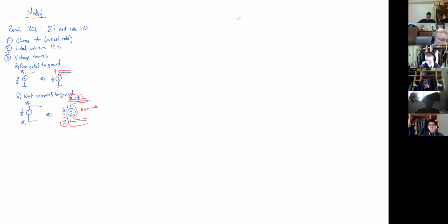All right, almost done. You'll do a KCL at every unknown node, or every unknown supernode. Having a known supernode doesn't make sense. And you'll never do it at ground.